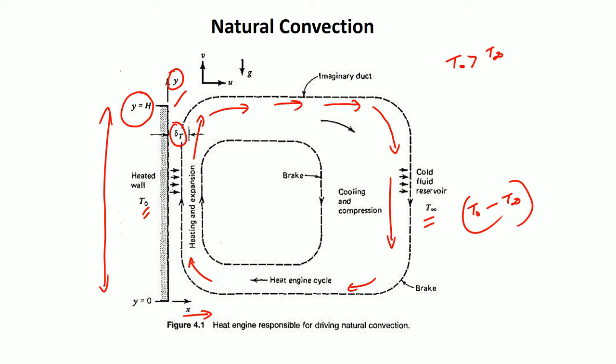Okay. So, what happens, the air, or whatever is the fluid medium, usually it is air in most of the common application cases, gets heated, it rises, it becomes less dense, that is, it becomes lighter and it rises. At the same time the cold reservoir fluid is displaced. So, it basically drives that particular pattern that we see over here. This natural convection loop that you create is pretty much like a heat engine, okay. So, how is it like a heat engine? Let us look at the steps of the heat engine.